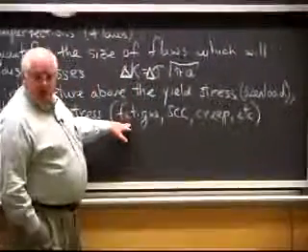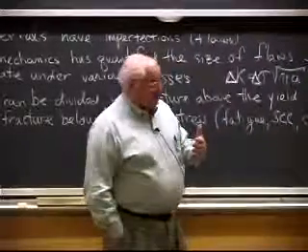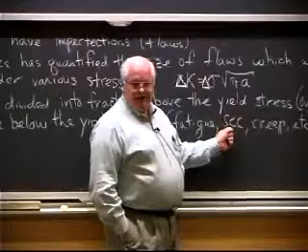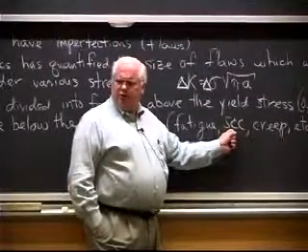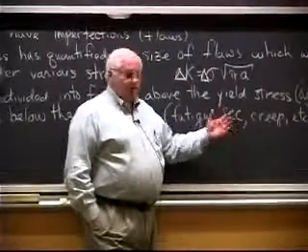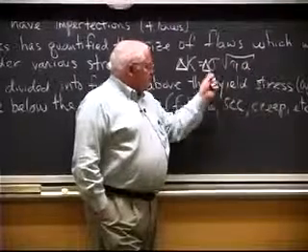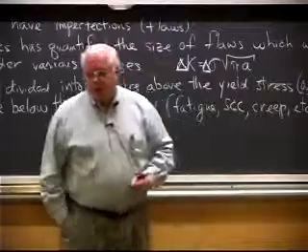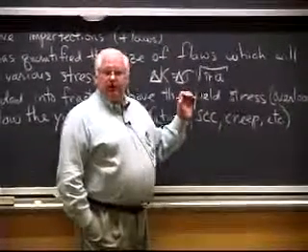Usually with fatigue, you're fine as long as you're at stress levels below half. But with stress corrosion cracking, sometimes you have to be at stress levels only 10% of the strength of the material, which is why you really want to design away from that. That's some of the problems General Electric had. I did mention the General Electric problems in the nuclear reactors, right? The stress corrosion cracking they had cost them a couple of billion dollars. So you've got to control flaw sizes, control stress, and control your environment. You have to design things for the proper temperature and whatnot. But you do all those things, and then things still fail.